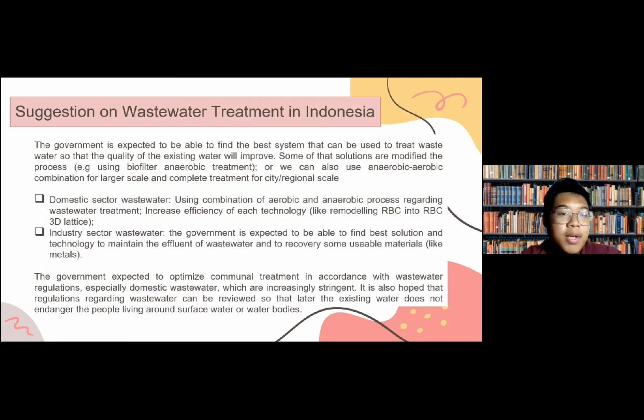Okay, so these are the suggestions on wastewater treatment in Indonesia. The government is expected to be able to find the best system that can be used to treat wastewater so that the quality of the existing water will be improved. Some of the solutions are modifications to the process, for example using biofilter anaerobic treatment, or we can also use an anaerobic-aerobic combination for larger scale and complete treatment at city or regional scale.